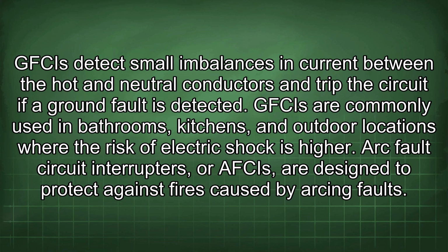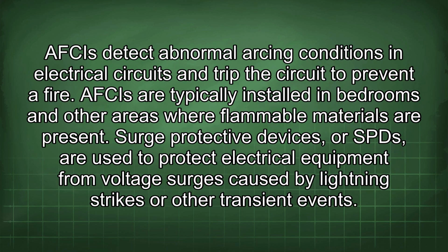Arc fault circuit interrupters, or AFCIs, are designed to protect against fires caused by arcing faults. AFCIs detect abnormal arcing conditions in electrical circuits and trip the circuit to prevent a fire. AFCIs are typically installed in bedrooms and other areas where flammable materials are present.